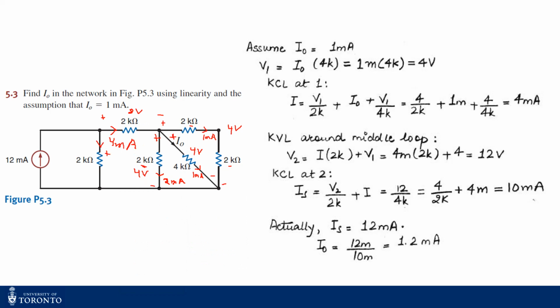So this should be plus, this should be minus. So if I apply KVL, so this V, let me call it V1. All right. So what should be my V1? It's minus V1. Yeah, I'm going clockwise. Then it's plus 8, right? Then it's plus 4 is equal to 0, right? So my V1 should be 12 volt, right? My V1 is 12 volts.